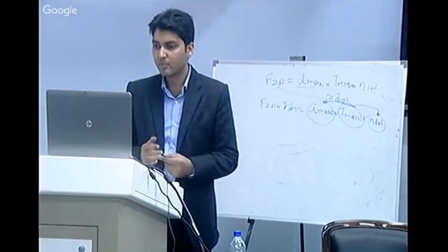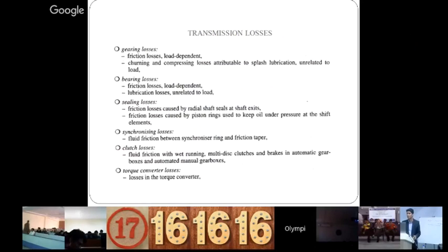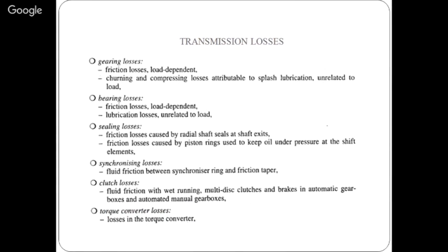So for that, and transmission losses, the new torque which I specified earlier is the transmission efficiency. Now transmission efficiency contributes to gear losses, the sliding over there in the gear, the bearing losses. When we preload the taper roller bearing, has anyone seen the taper roller bearing arrangement? Preload taper roller bearing is basically in 2 cups. When we preload it, then it will consume a force.